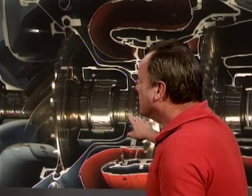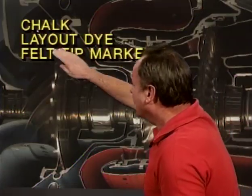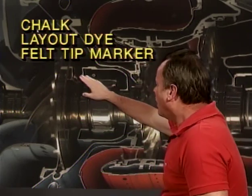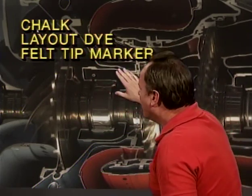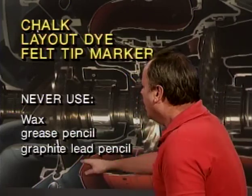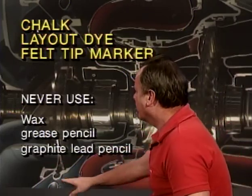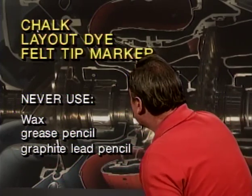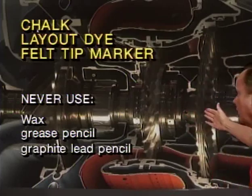So these turbine engine components can only be marked during inspection with materials allowed by the manufacturer. These include chalk, layout dye, and a felt tip marker. A commercial felt tip marker is often allowed. But you don't want to mark it with just anything. Things that are generally not allowed are wax or a grease pencil or a graphite lead pencil, because you may find that your little bit of marking caused later damage down the road.